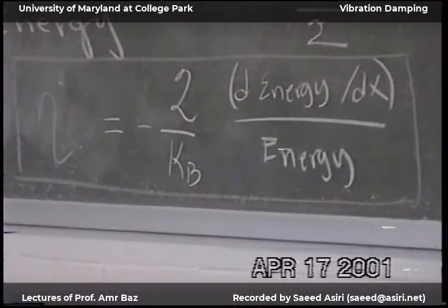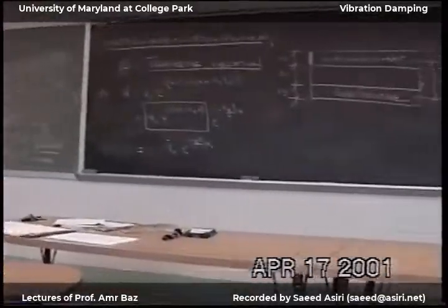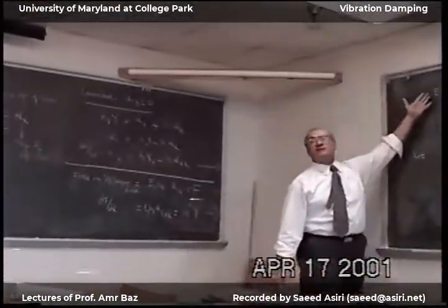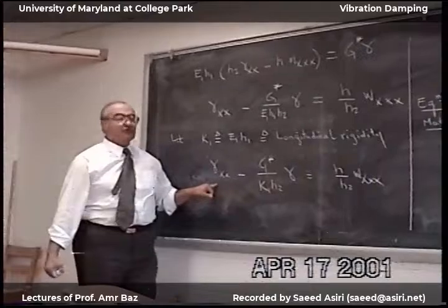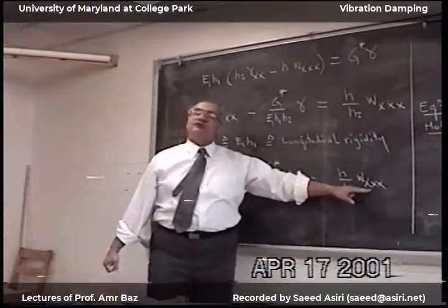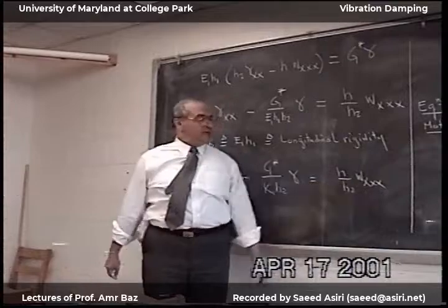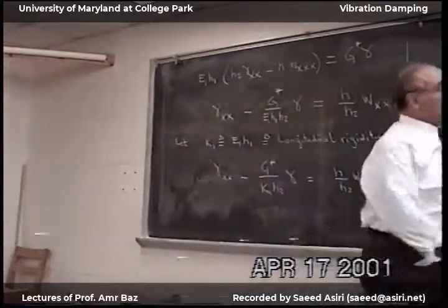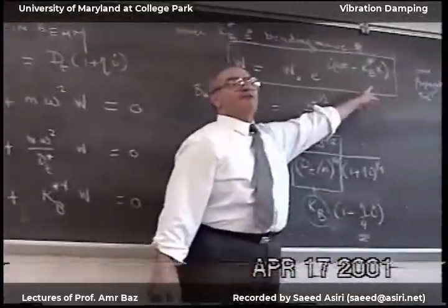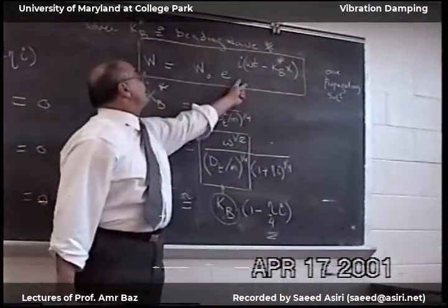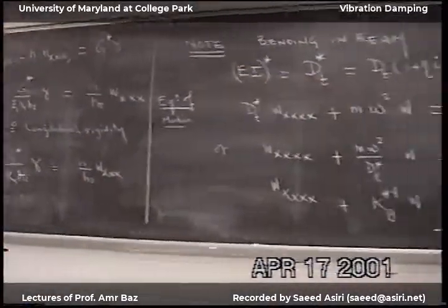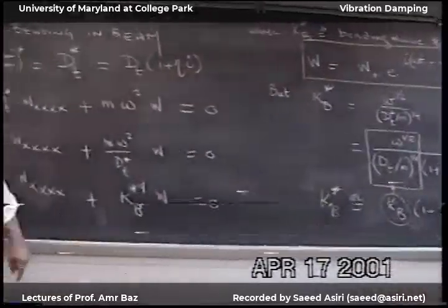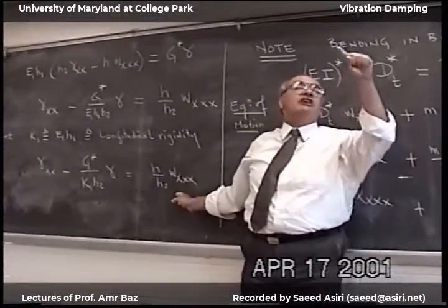So now we have this system, and this system is represented by this equation, and this equation gives us the shear angle as a function of the transverse deflection. Transverse deflection, we have it in this form. So I can put this here, and for any position x, I can solve this differential equation. I determine the shear angle.